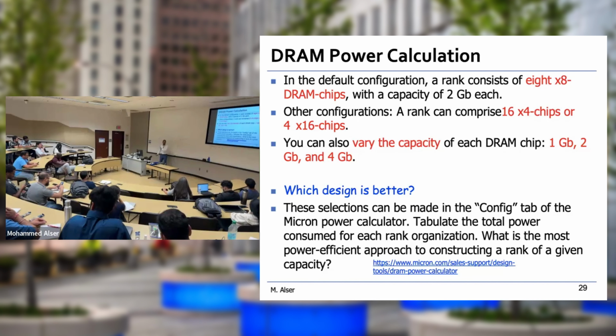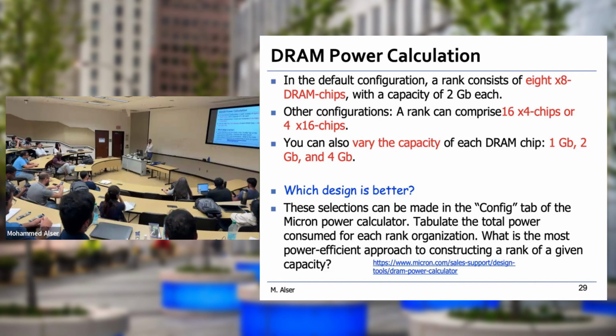And remember, when I send a refresh command, it means the memory controller is blocked from sending any command for that period of time because the DRAM is busy doing the housekeeping, refreshing all rows. So of course, it's going to impact the memory controller or the CPU, and they should communicate together for a correct workflow.